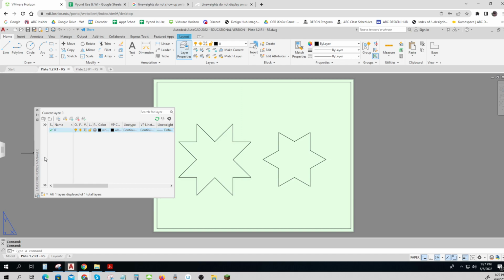To make a new layer, there's a little thing here that's a new layer, Alt-N, or click that. And I'm going to make two new layers. One is called Geo. Those are for lines that I draw. And another is called dim-text, and that's for annotations and things like that. So let's set the colors.